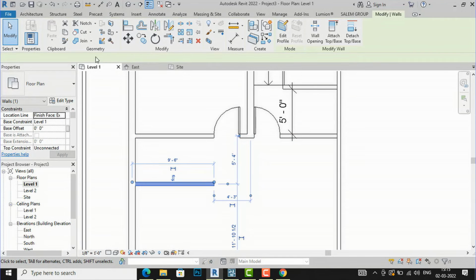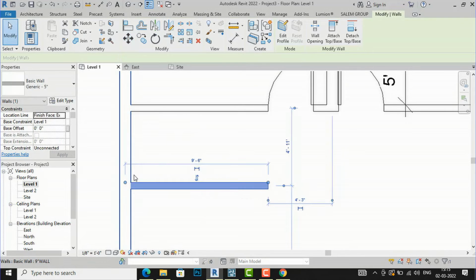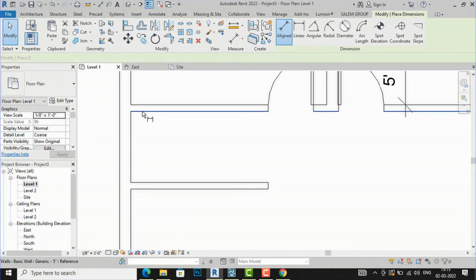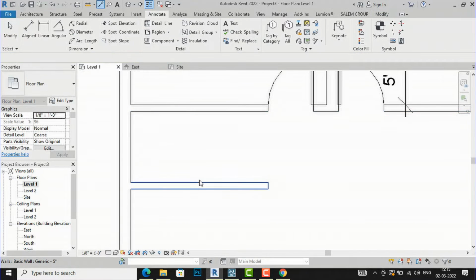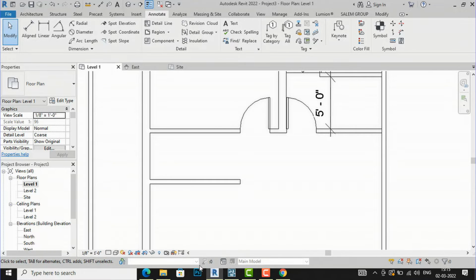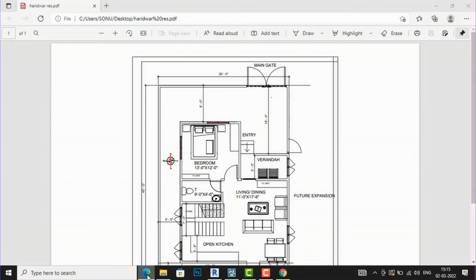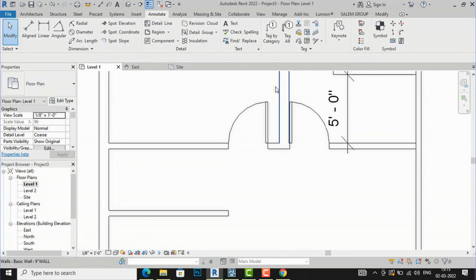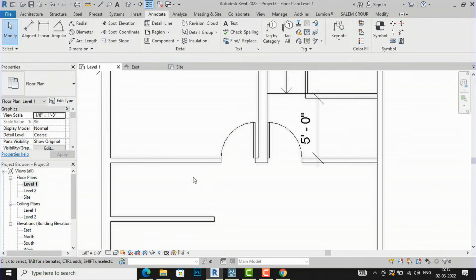So I will move inside 5 inches. So I will use this corner and I will type 5 inches. And now if you take measurement, this is 4 feet 6 inches. It's perfectly fine. And now I am going to use 9 feet as the length of this pallet area. So I will place this over here, this door, and now I will draw a wall here.